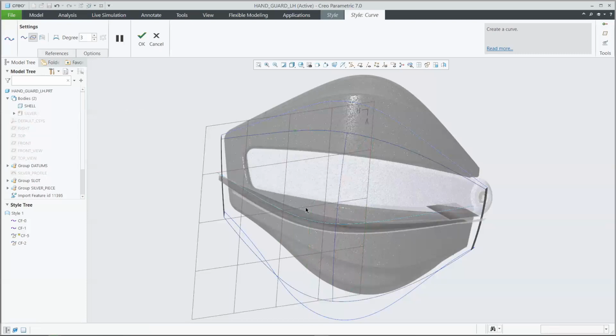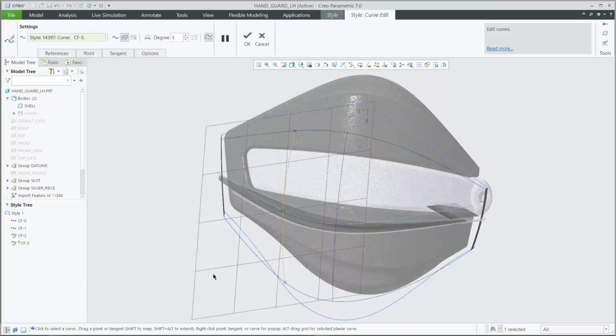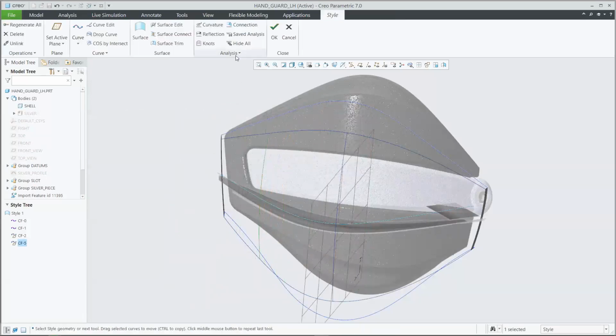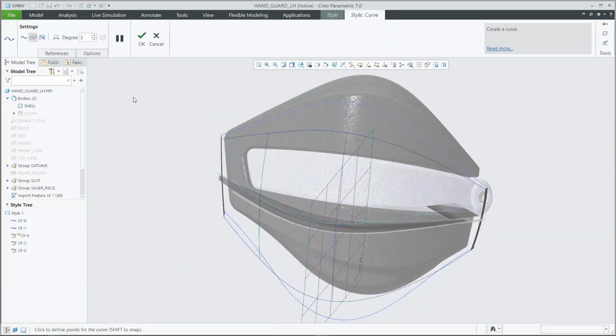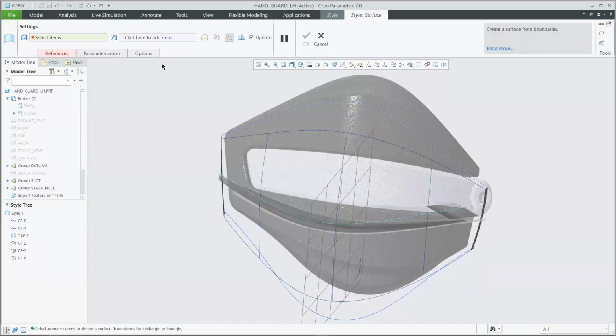Tons of different options that we have available. What this one means is that I'm going to select on a point on one of these curves, and then the plane that's created is going to be normal to the profile sketch that we selected. And you can see as you move it along, it's going to stay normal along that curve. We'll do the same sort of thing with the third curve here, again, using the radial planar option. We'll put that over here on the right-hand side of the model. And that's looking pretty good.